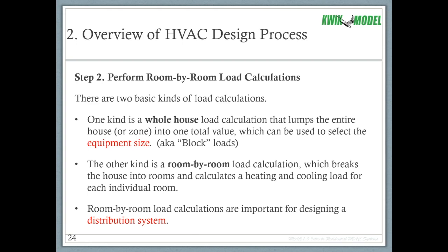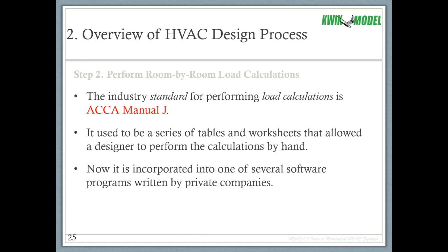If you do room by room load calculations, obviously you can just add those up to get your whole house. But if you only do a whole house load calculation, it's pretty tricky to then parse that out on a room by room basis without actually calculating room by room loads. Room by room load calculations are very important for designing a distribution system. The industry standard for performing load calculations is ACCA Manual J. It used to be a series of tables and worksheets that allowed a designer to perform the calculations by hand. Now those tables are incorporated into one of several programs written by private companies. There's several of those out there. We're going to do an example house later using one of the newer ones that's available.